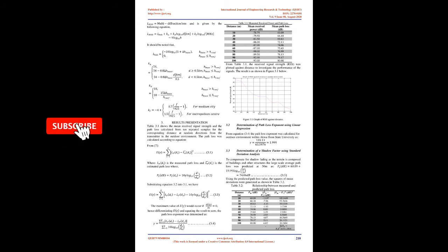The path loss is provided for isotropic antennas with provisions for others. 2.2.2 Okumura-Hata Path Loss Model. The Okumura path loss model is an empirical-based model for irregular terrain. The Okumura-Hata model is the most popular model, based on extensive measurements made in and around Tokyo in 1968, where